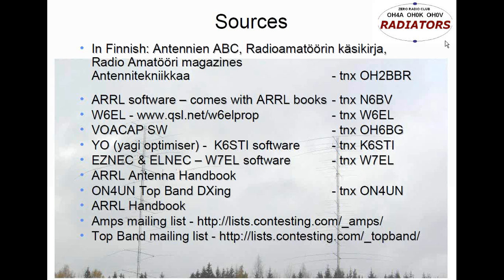Actually, this array of 6 Yagis on 20 meters, I still have it at OH4A, but I have been adding all bands to both towers. So I have all 6 bands on both towers at OH4A. I have experimented that it matches the expectation broadside towards USA, both short and long path. So I'm getting the additional gain, and I'm getting the additional attenuation to Europe, the signals that are close by.